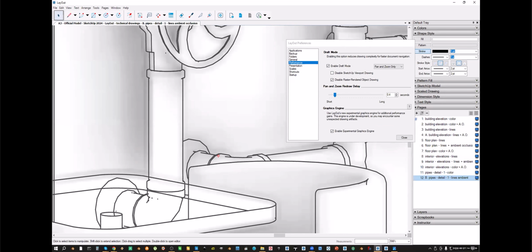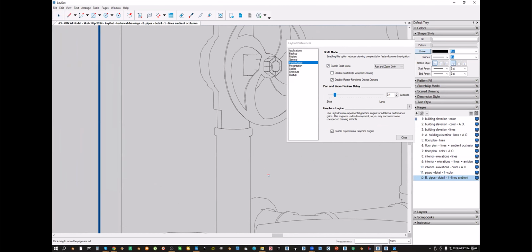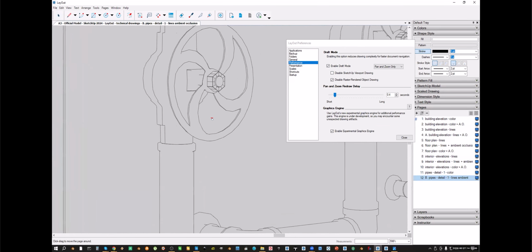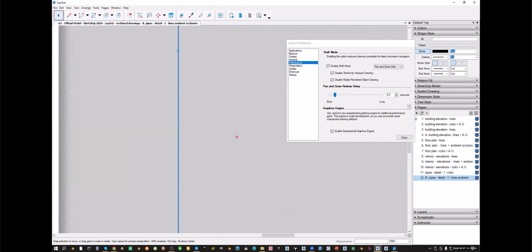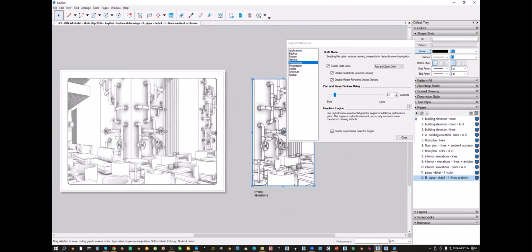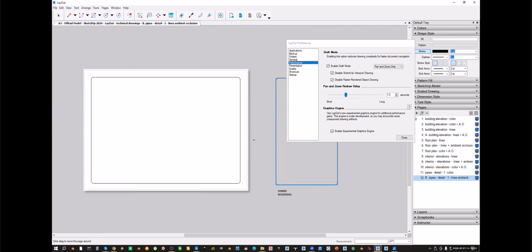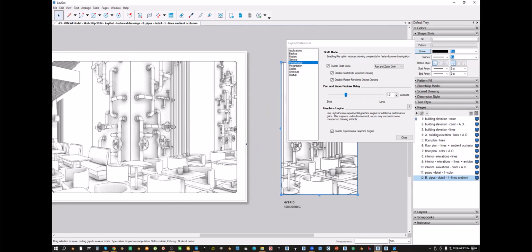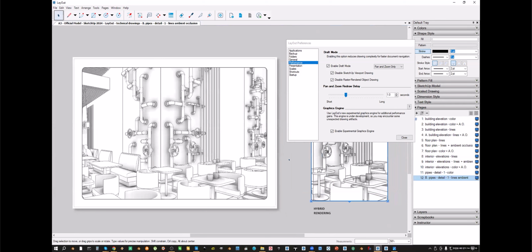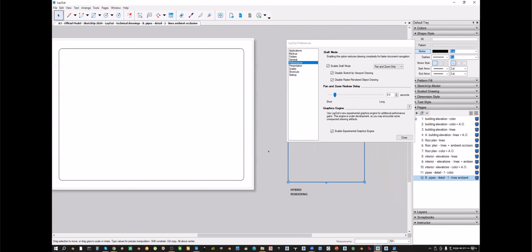The thickness of the line, let me just, no, I won't recalculate that for now. So if we start to move, we only have those very thin vector lines during the movement. If we turn on both, there will be no displayed SketchUp objects at all. So here you can choose between the refresh delay or redraw delay. It's really, again, depending on the file size. If it's going to be a huge file, probably it should be longer. But you can also control it with the letter K.